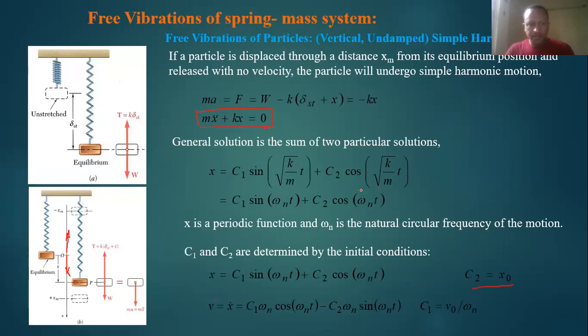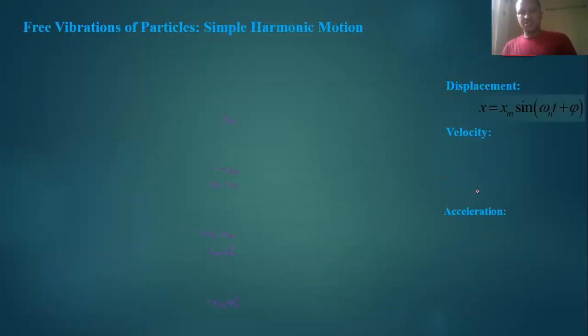We can apply this to this equation. So finally, it gives us x of t is equal to, okay, C2 is x naught, C1 is v naught over omega n, times sine of this term. It is a simple substitution actually, it's not required.